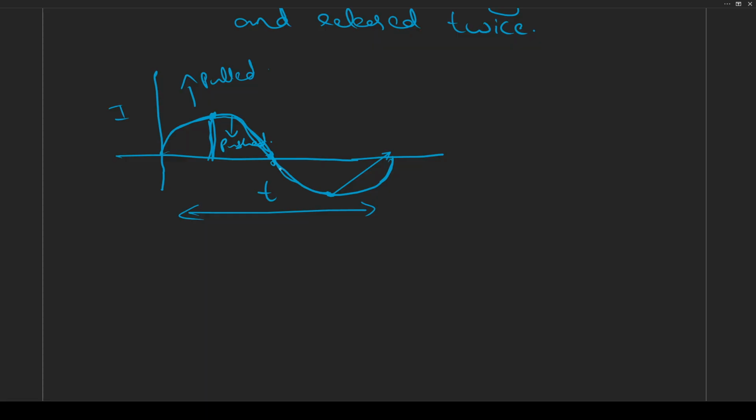Once more the current is increasing in the other direction, but still increasing, so the string gets pulled. The current will once more decrease, and again the string will get pushed. In a single cycle of AC, the string is pulled two times and pushed two times.